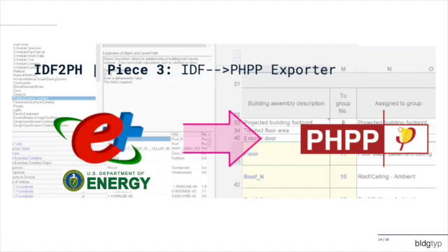Now, technically, you don't have to create this in Grasshopper. This tool can actually take an IDF file which is created in any tool. You can write it by hand, do it in Design Builder, do it in whatever tool you want, and then you can take that IDF file and convert it into a PHPP. But this is custom made to work really well with the Honeybee tools, and it adds some additional functionality if you use it within the Grasshopper world. But you don't have to by any stretch. It can operate independently as just a straight IDF to PHPP exporter or adapter.